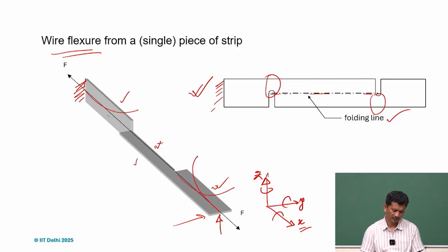So we can see there is a compliance in the z direction as well. Likewise, if we talk about the rotation, yes, it's a torsionally compliant member. All three are torsionally compliant in X, so it can twist easily. If it's in the Y direction, this can twist easily.